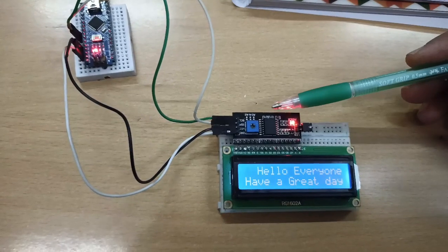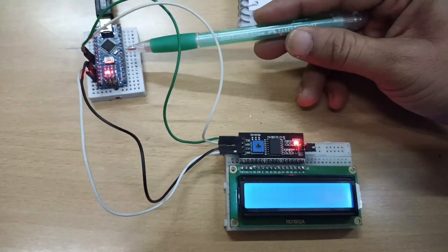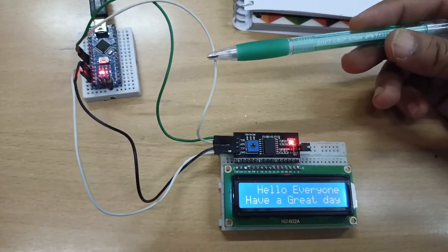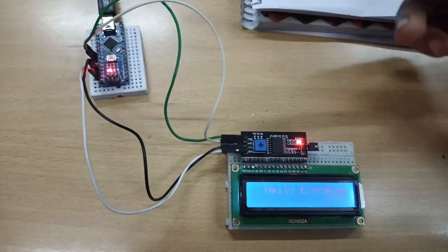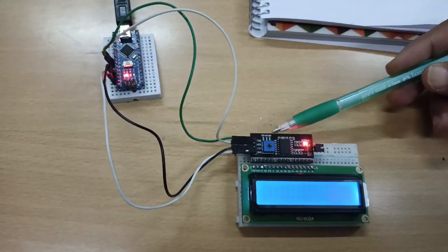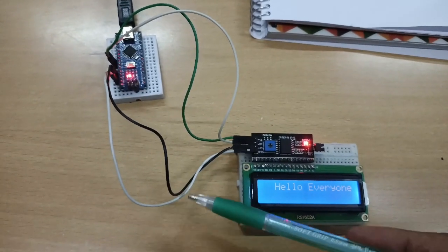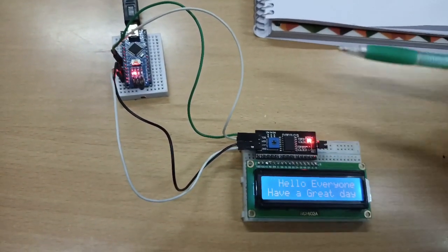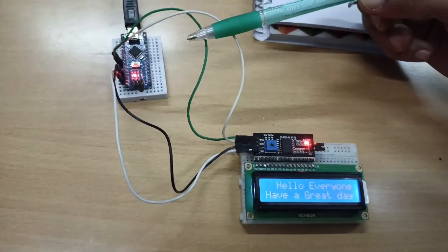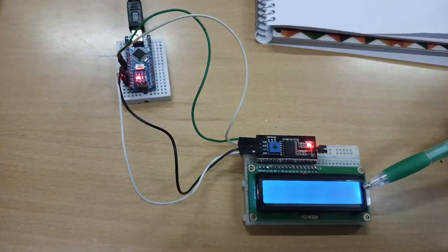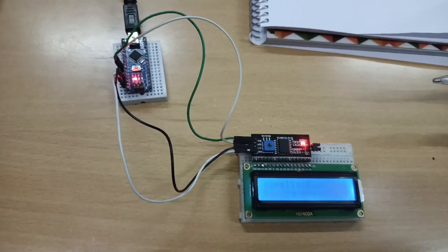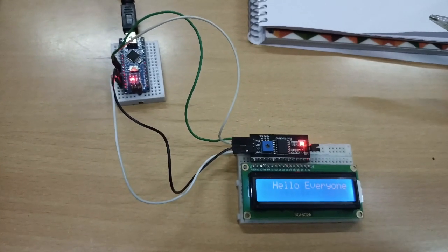and this PCF8574 board is connected to the Arduino Nano board through the I2C protocol, where the green wire is the SDA pin and the white wire is the SCL pin, serial data and serial clock. So the Arduino Nano board and PCF8574 are interfaced through the I2C protocol. The black and white wires are power supply wires. With the help of this PCF8574 board, with just 2 wires, we can interface a 16x2 LCD module with the Arduino Nano board, which is very helpful for us to monitor the status of a lot of embedded applications. Thank you very much.